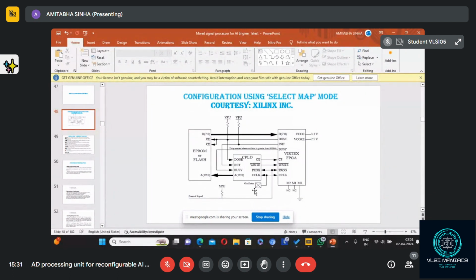So here, why have I used a CPLD? Because if I don't use a CPLD, then I have to use a lot of logic circuits, and I have to design a controller which will generate all these signals: write bar, prog bar, clock bar. Instead, these days the trend is to reduce the overall design time. Why?